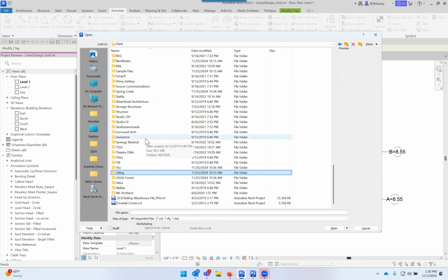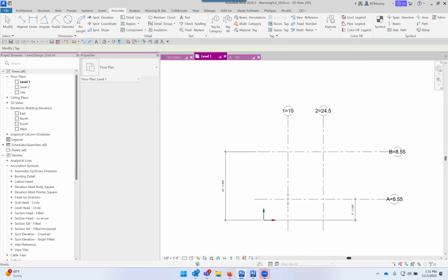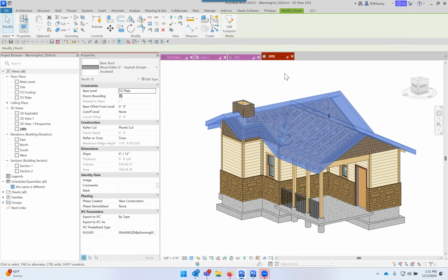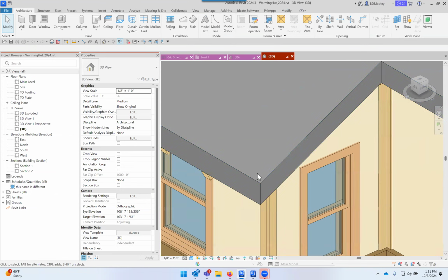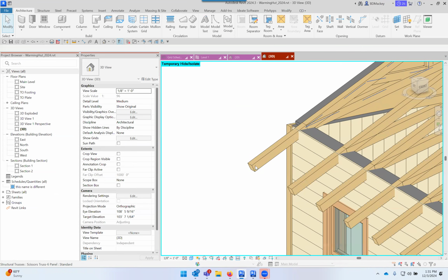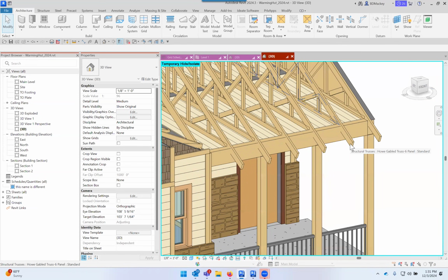Theoretically, Sarah, follow-up question, are you actually modeling the joists? So you just want, oh, structuralist. Do you want your roof to look parallel? You're not modeling those, so you want the roof not to be plumb. Is that what your bigger question is? So not the actual joist, but the roof itself. Because the joists by default are always going to come up square, no matter how you model it.